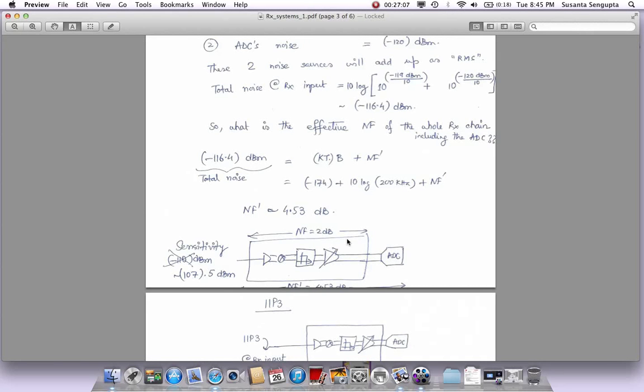So we have gone through gain, showed you some exercise of how we calculate the maximum gain, and then as the input level changes, over a wide dynamic range of the input, how we change the gain is based on two things: ADC noise, how much will get reflected back at the input, and also the swing. Those are the two things that we will constantly monitor. When we go through the exercise, I've talked about it too many times, but have patience and you will see how we do that. The AGC, the automatic gain control, over the wide dynamic range of the input.